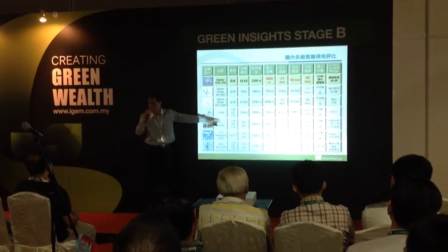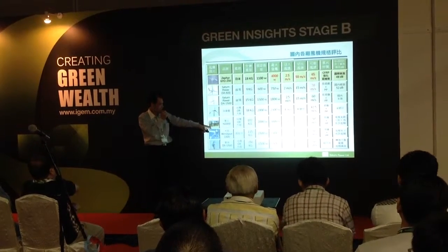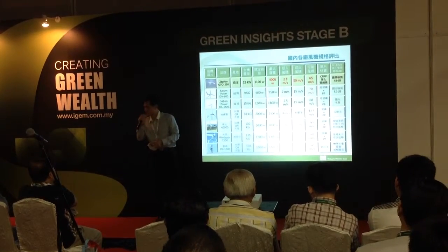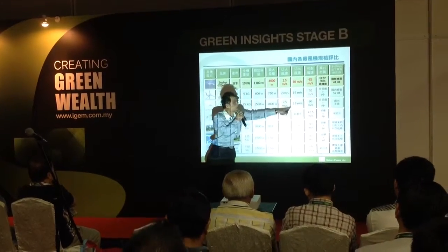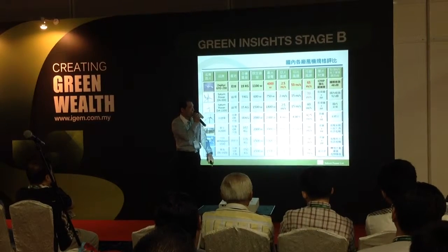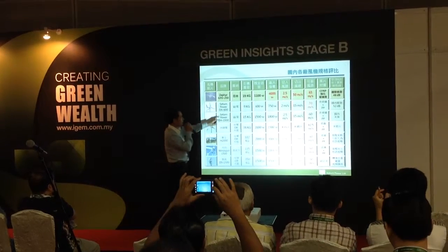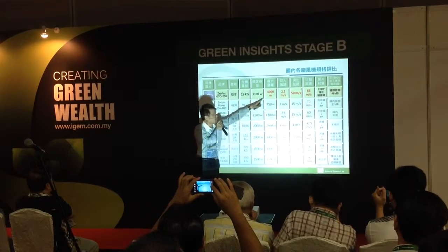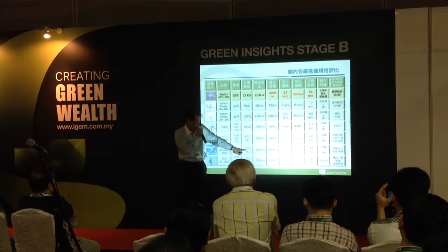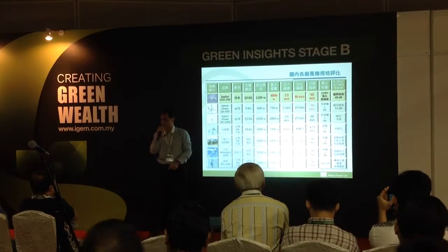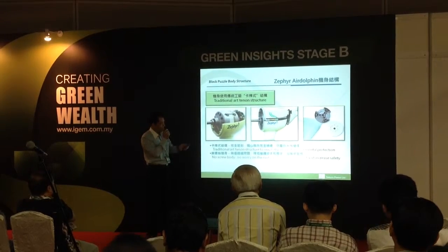And this is already a benchmark for all the available wind turbines we can see in Taiwan. Now after my introduction, everybody can focus on the cut-in speed and cut-out speed here. And the second thing you should pay attention to is the weight. It's 90 kilograms for 400 watts. You see the rest, it's 135 for 1.8 kilowatt. So it's a huge difference. I will skip this design.